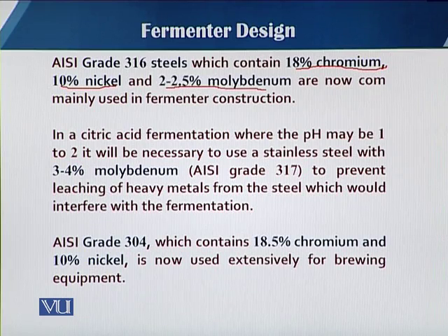But with this grade, when there is acidic fermentation, especially citric acid fermentation, the pH in high citric acid production drops to 1 to 2, so highly acidic conditions. In such a case, 316 grade stainless steel cannot withstand the properties which we require.